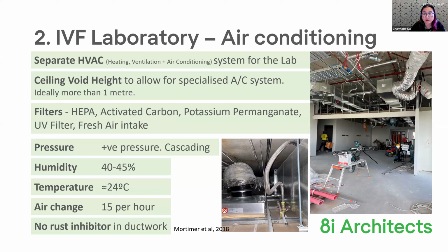So one of the things to look out for if you are looking for a new space and thinking of putting an IVF lab in is to have a look at the ceiling height void. The ceiling height void is the height between the top of your ceiling to the underside of whatever structure the building is. It might be the roof, it might be the concrete slab of the floor above. That distance, the more space you can get in there, the better for putting in a dedicated air conditioning system for your lab. As you can see in these photos,